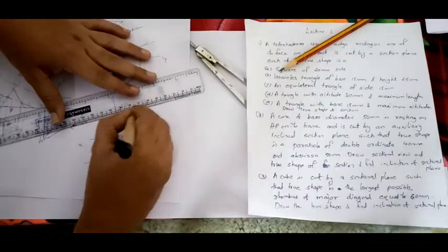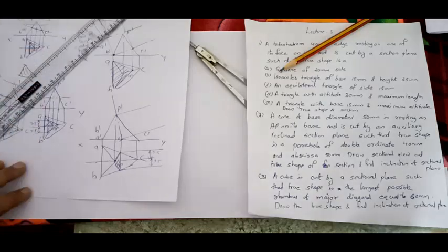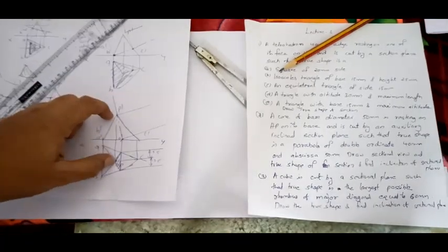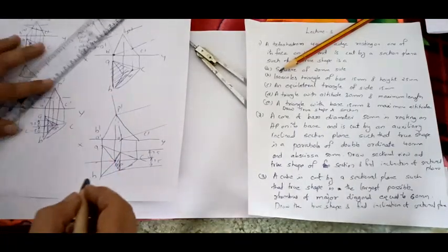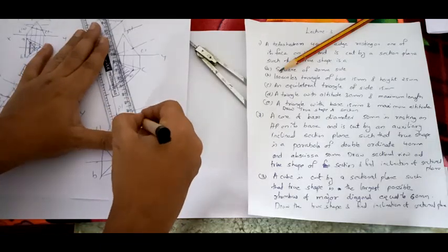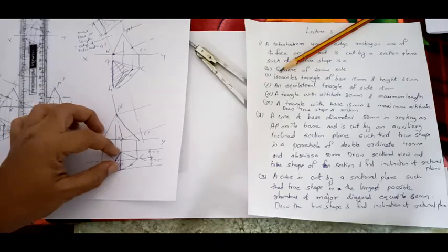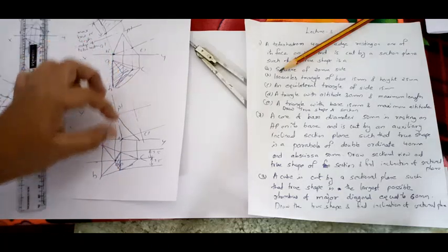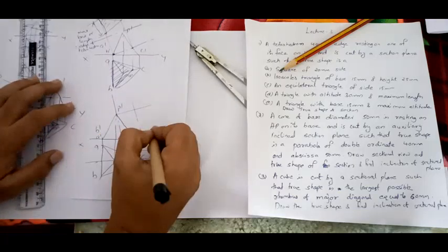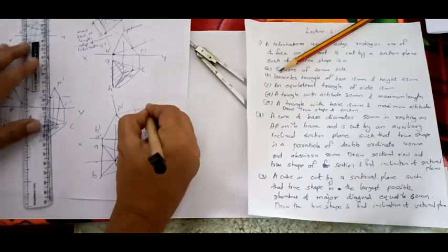So draw perpendiculars from here. Two perpendiculars you have drawn. Now take from this point, you have to take this xy line, right? So for that you have to draw a line parallel to this line outside the figure. Now on the xy line, take these two distances. These two distances will be here. Cut it here, 1 2. Then take this distance, cut it here.